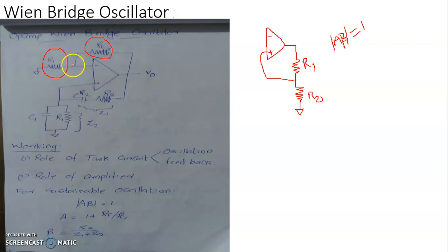And we already know that in the case of an Opamp there is no current flowing through this path, so this is always a balanced bridge. However, there are some conditions to be satisfied for the balancing of the bridge.